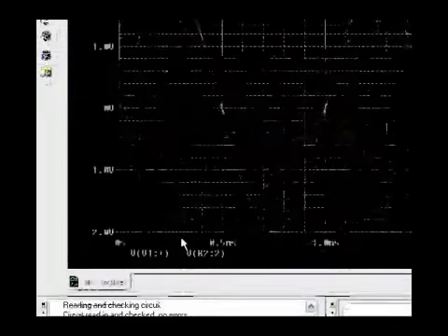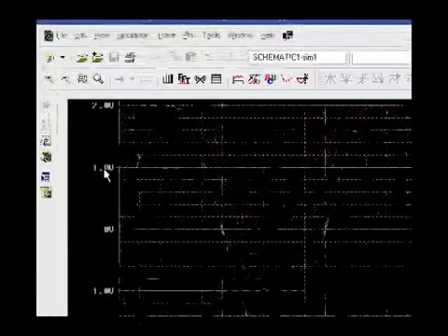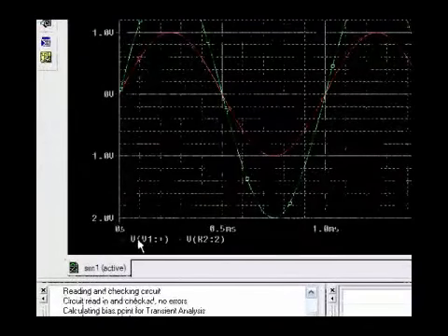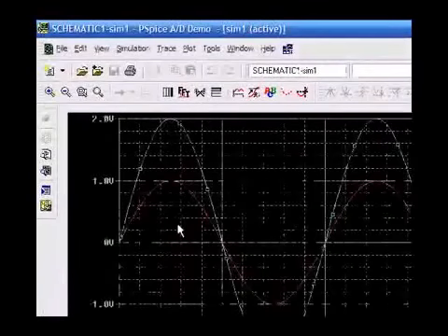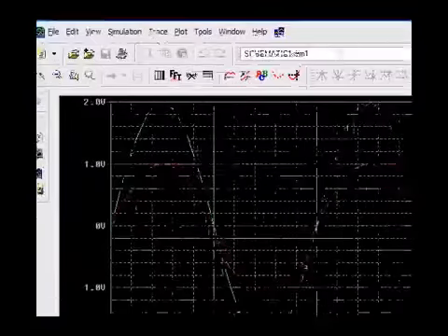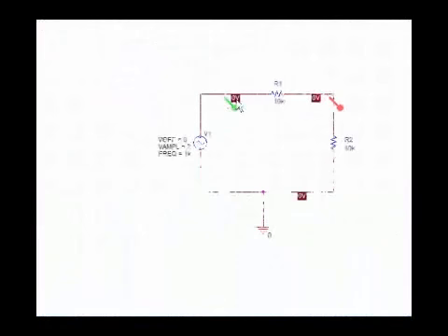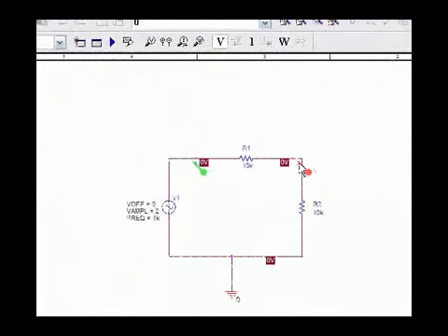So you'd see in the red is the voltage across R2. Half of the voltage appears, 1 volt, at R2, and then V1, the one in green, is our input voltage of 2 volts. So our voltage divider did work. And we could see at the circuit we have 0 volts at both because there is no DC. So these voltages here, by pressing the V, show us the bias voltage in the circuit.